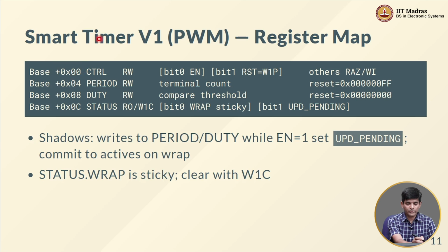How many registers do we have? 4. Even if you consider the fact that each register is 4 consecutive address locations, this is a total of 16 addresses, and we have 256. Like I said, we are making this choice because it makes it very easy for us to do bit manipulation and alignment of the addresses and even the decoding by just choosing a chunk of addresses out here.